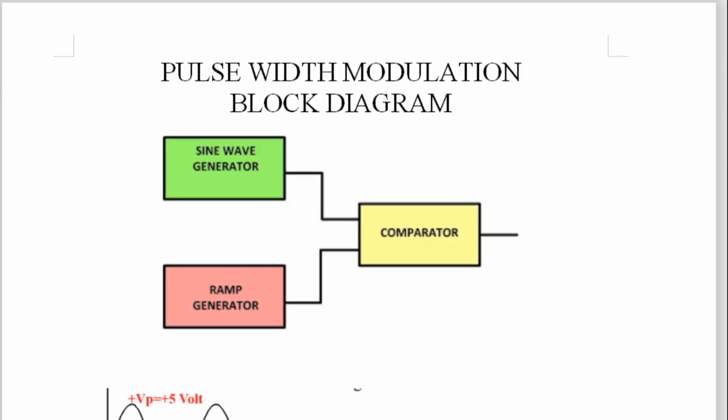The width of the pulse is changed. And then how to generate that output? The question is how to generate that output. Now here you remember one thing which is very important. Here we are using different carriers. Not a square wave, a square wave is not a carrier here. In this pulse width modulation, our carrier is nothing but a triangular wave.